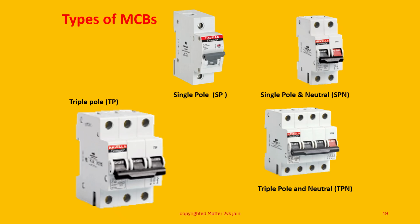Friends, this slide shows the types of MCB. This is one single pole. The other one is single pole and neutral combined. So when you operate this dolly, both the neutral and phase current get opened or made.